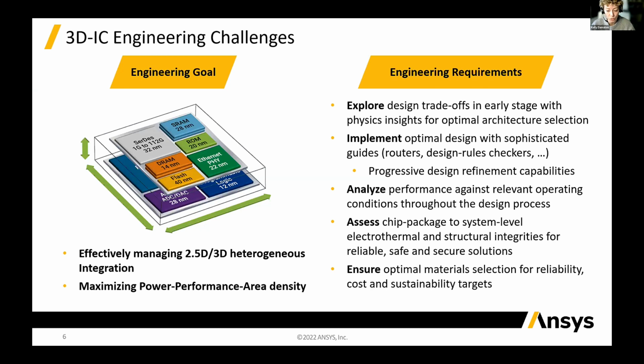The sign-off phase should include the accurate modeling of TSVs and the interposer, as well as detailed analysis of the different physics aspects: signal integrity, power integrity, thermal integrity, and mechanical. Mostly all of those steps of the design process should be revised to take into account the particularities of the 3D IC architecture. And if you're a designer, you already know by experience, or you can guess if you're not a designer, that this new approach for going from monolithic chips to 3D ICs would require new tools and methodologies to be adopted in